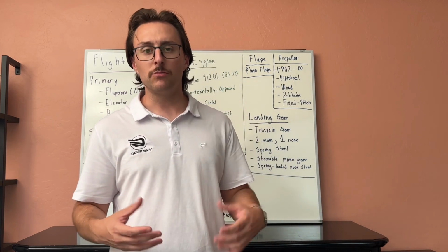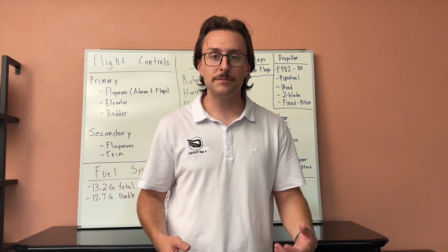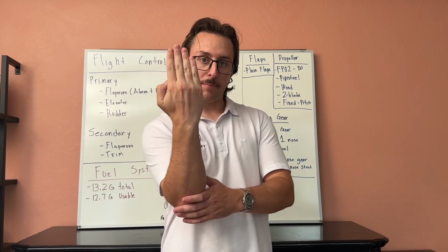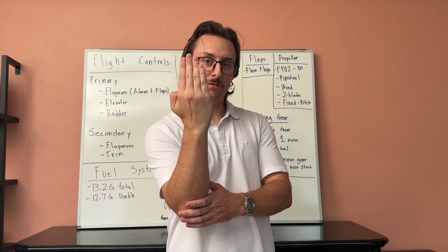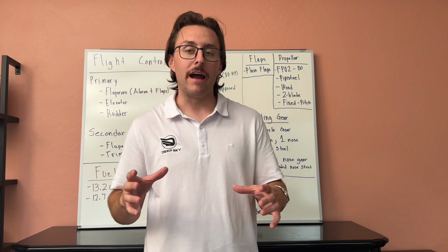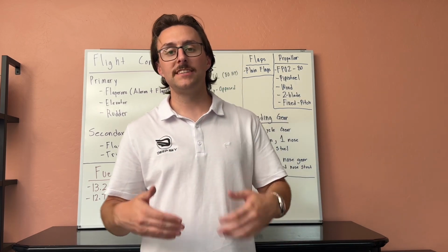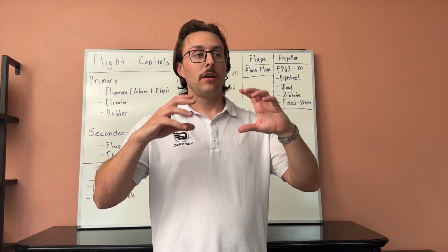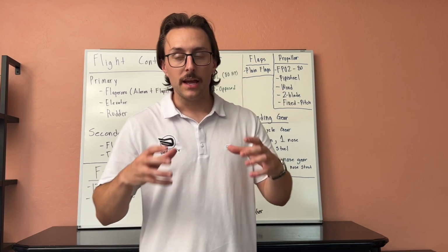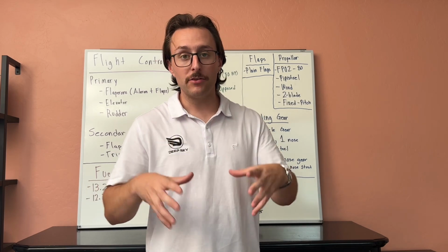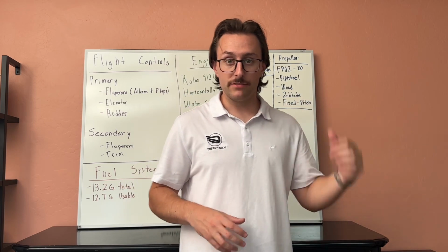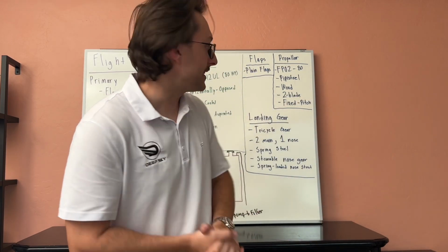What does it mean by fixed pitch? Well, there's 2 types of propellers: constant speed and fixed pitch. With constant speed, the propeller blades will actually move in order to create a constant RPM on the aircraft, which will help with fuel efficiency and stuff like that. But when Deep Sky acquired this plane, the only kind of propeller you could have on a light sport aircraft was the fixed pitch. They have now since changed that, but at the time that was the case.